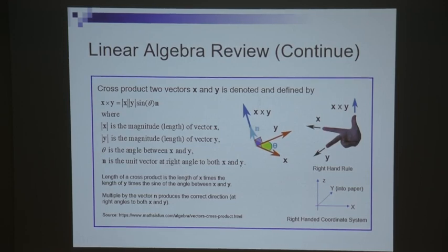So this is important because you'll be using something called a right-hand coordinate system. When you want to attach a frame to the base of your robot manipulator, you see that we draw the coordinate on the cylinder. So this frame, the x, y, and z coordinates, will have to be defined according to the right-hand coordinate system, meaning that if I specify my x and y, my z will always be defined in this manner.